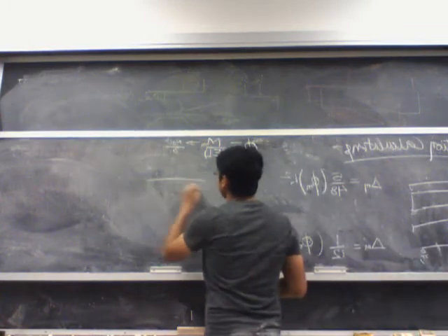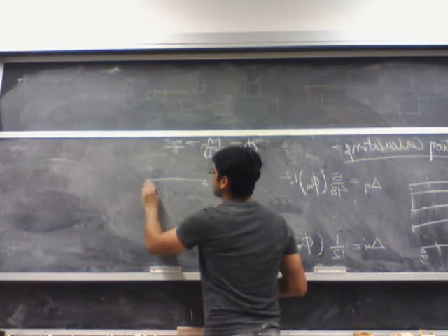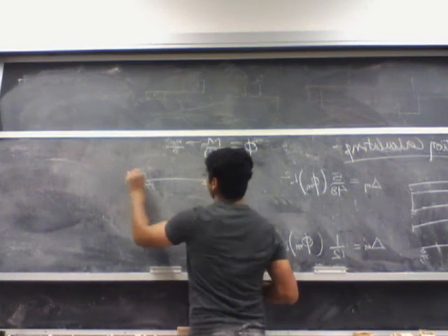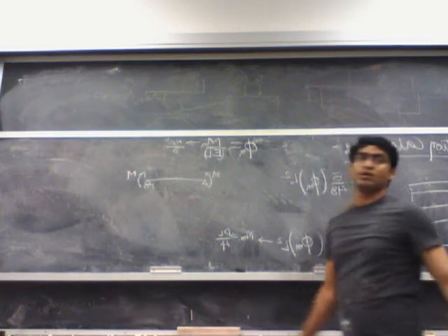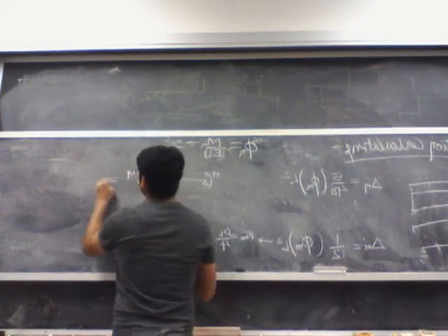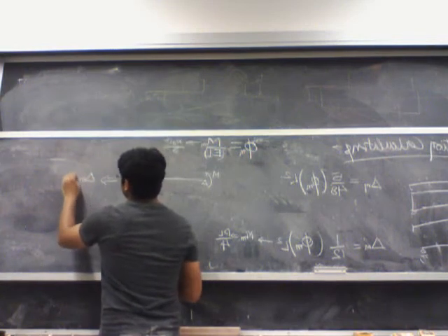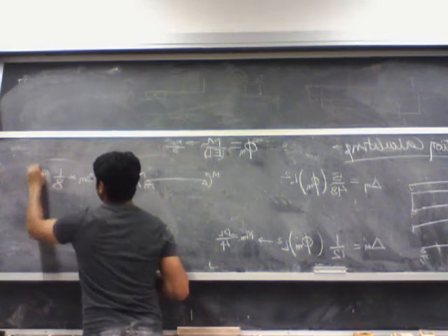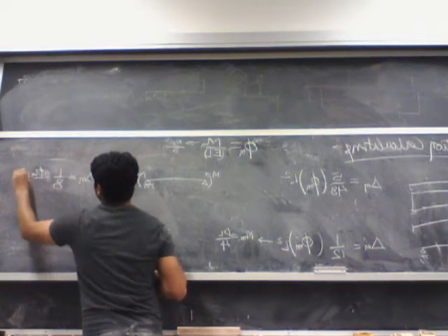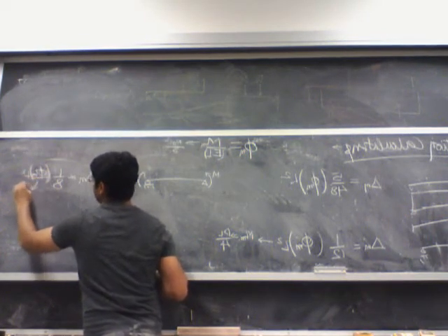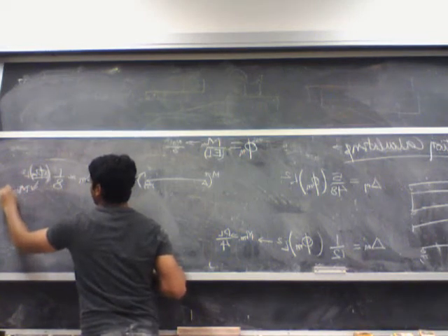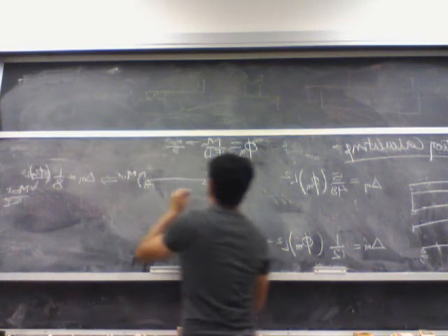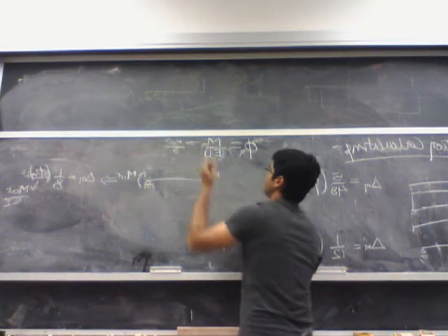And the third case that we might have, which generally occurs, is a case where you have a constant moment throughout the span. In this case, the deflection at the midspan is given as 1 over 8, again phi m L square. Here phi m is simply M external divided by EI.